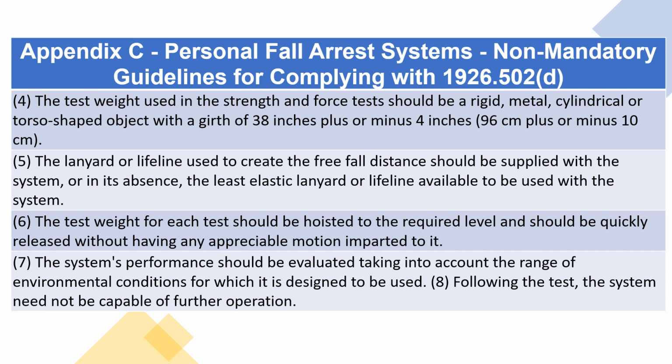5. The lanyard or lifeline used to create the free fall distance should be supplied with the system, or in its absence, the least elastic lanyard or lifeline available to be used with the system. 6. The test weight for each test should be hoisted to the required level and should be quickly released without having any appreciable motion imparted to it. 7. The system's performance should be evaluated taking into account the range of environmental conditions for which it is designed to be used. 8. Following the test, the system need not be capable of further operation.